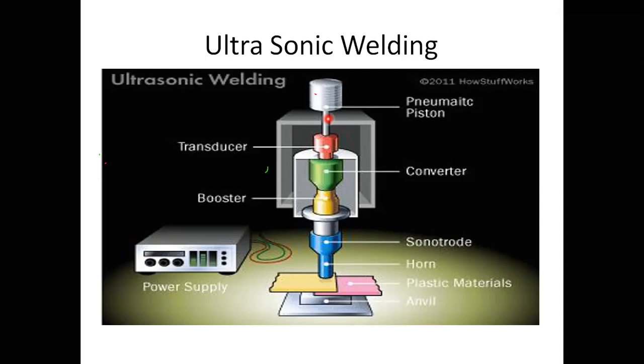Then what happens? The welding plate deforms to a plastic stage where the face-to-face contacts are there, or you can say the region of contact. Due to the mechanical force and the friction, heat is generated, which helps the plastic deformation of this metal, and then it will be welded to each other. And this is applied for a wide variety of dissimilar metals, where we are going to join.